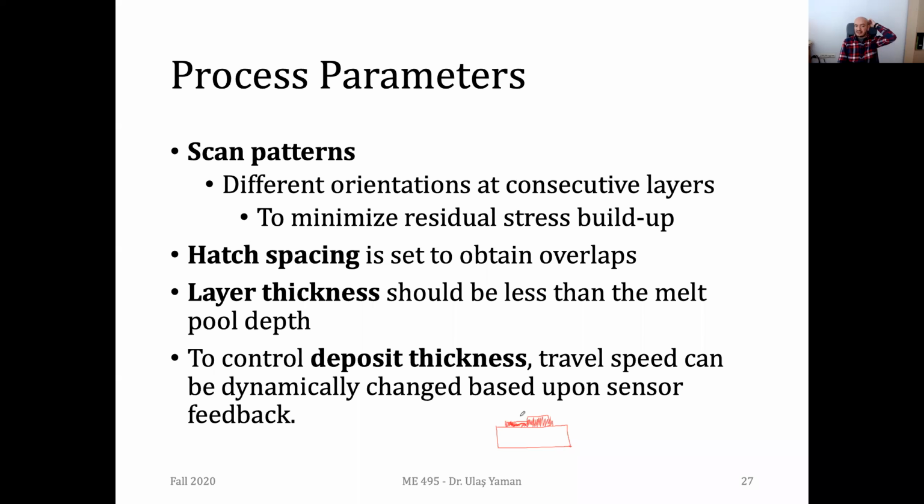And if you see with the help of your vision sensors such a difference between these two regions, then you may decrease the speed here. You have, let's say, VA, and this is VB. VA should be less than VB in the fixing part or in the next layer, so that you'll be depositing more material here in the upcoming layer and try to adjust their height. And in the other layers, you'll have a perfect plane. This is how we do the fixing with the help of the sensors and some other parameters.